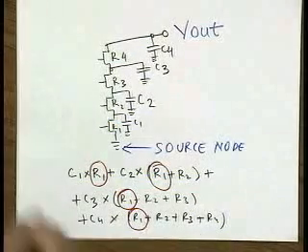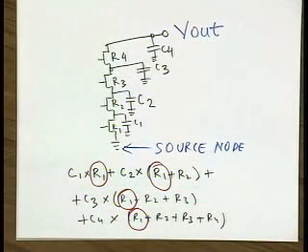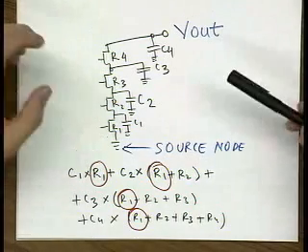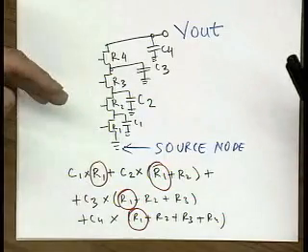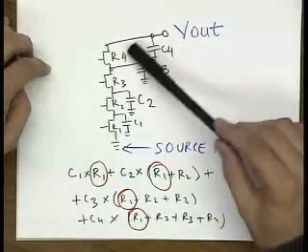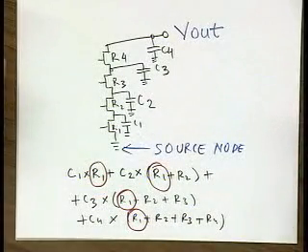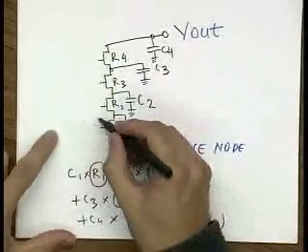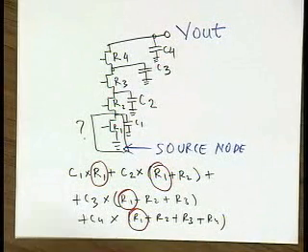So what this tells you basically is two things. One, you first have a quadratic increase in your propagation delay because you have both R's and C's adding up to each other, right? And second, now the question is, how would you change your sizing strategy, starting from all transistors being the same, such that you have a little bit better delay than you have in this case? What would you do to this guy? Would you increase its size or decrease its size?